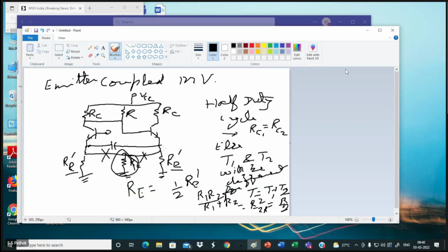Okay, what is this? This base is open here. I cannot keep it open, so I apply a voltage here, positive voltage VBB. VBB will be less than VCC, of course. So apply a DC voltage VBB here, it becomes your multivibrator, it will start oscillating.